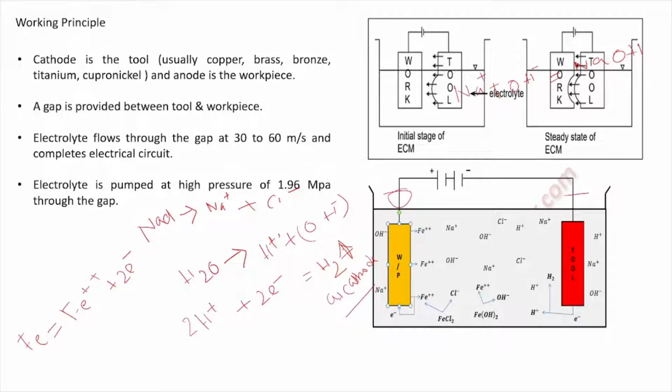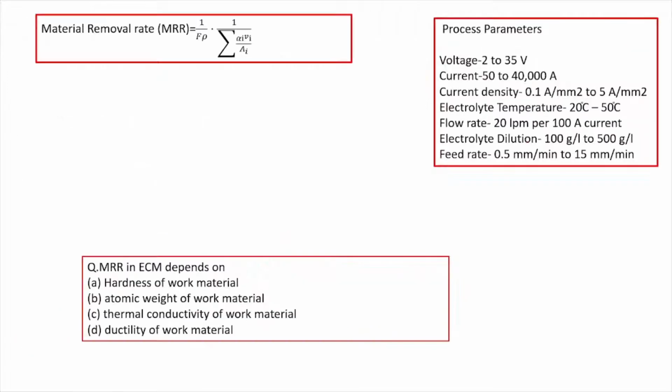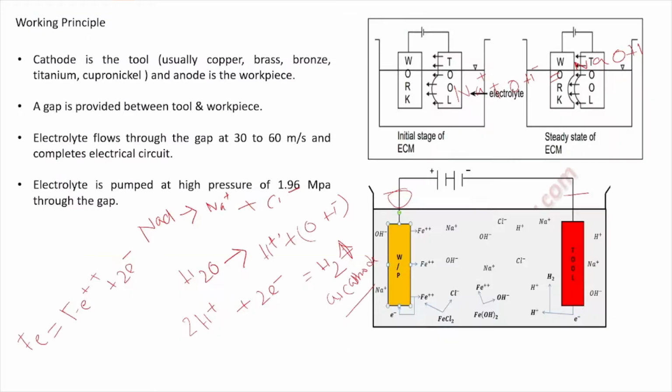We will see in the material removal process how all the laws of Faraday's principle are followed. Two dissimilar metals are in contact with an electrolyte, and the anode loses metal to the cathode. In this way Faraday's principle works. Here the workpiece is working as the anode, the tool is working as the cathode, and the electrolyte is electrically conductive fluid. That's all, right?